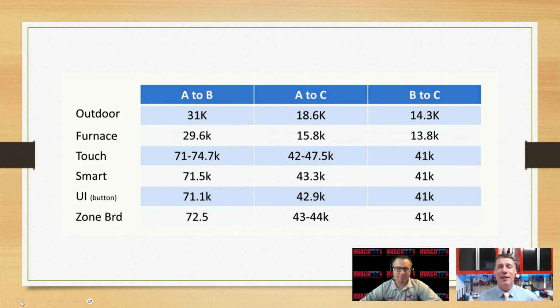This particular manufacturer goes deep enough to say, after you've powered everything down and given enough time for all of the capacitors to drain their voltage, you can disconnect these control wires and we can tell you what the resistance of that board should be, so that you know if your DC power supply is actually good or not. So they reference ohms and thousands, and if it's anything outside those parameters, and I imagine they give you a plus or minus 10%, that can tell you if your board's bad, if the power supply of your board is good.